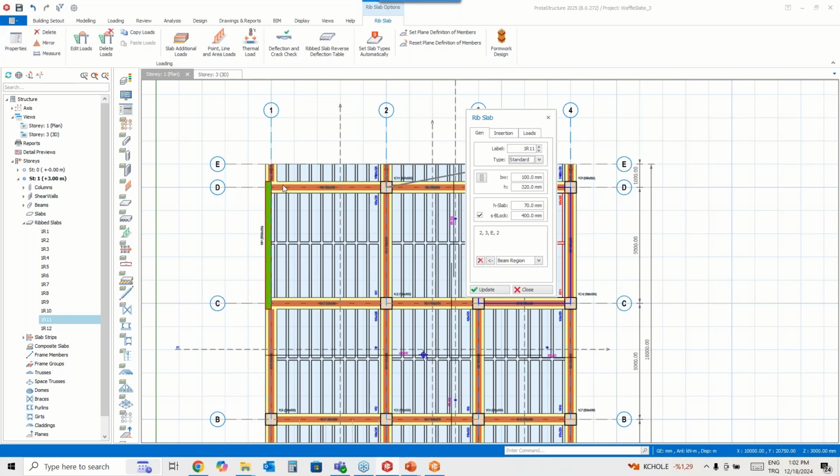If the section doesn't fit the reinforcement, what is the best solution for a fast change? You can increase the diameter and reduce the bar number, or you can simply increase the section. Otherwise, concrete will not be placed well, which might be a problem for us.